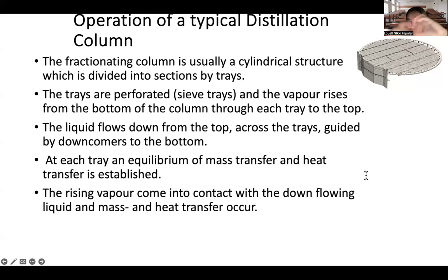So there is a mass transfer in between the processes and also heat transfer. There is a heat transfer from the hot vapor from your bottoms, which heats the descending liquids. Yung mga pababa na liquid, due to gravity, it's heated by the hot vapor. And then the liquid cools the rising vapor, which is hot rising vapor. So there is heat transfer.